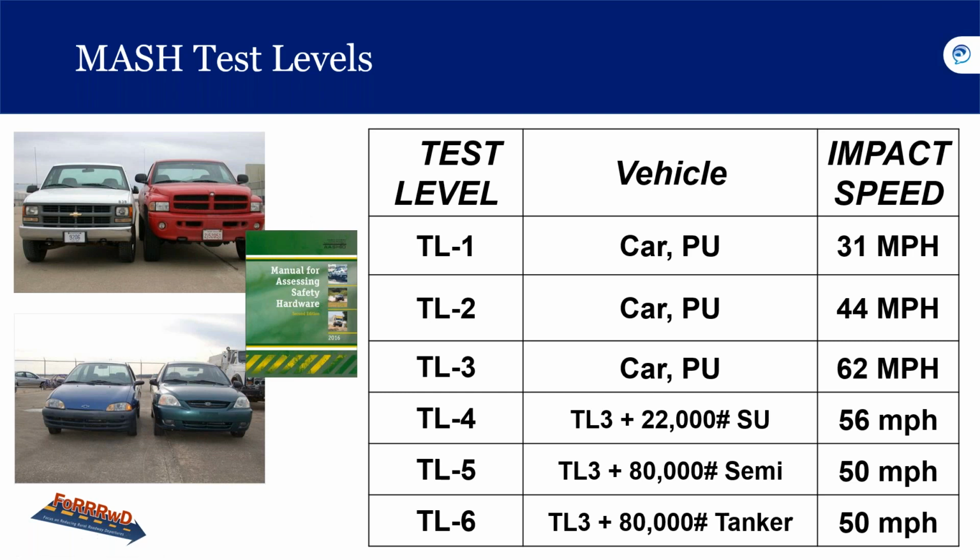So the other requirement of a barrier is proper in-service demonstration of acceptability or performance for its intended purposes. And that's stated in the Roadway Design Guide section 5. And so we have up here at the top, these two pickup trucks. We have a new test vehicle, which is a quad cab pickup truck of 5,000 pounds. The one on the right here, that's the new vehicle to test, has a higher center of gravity and more closely represents large SUVs.